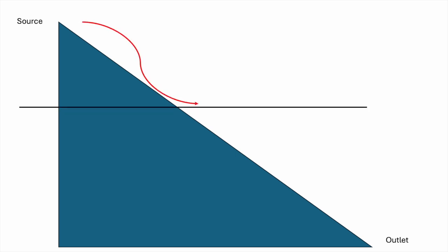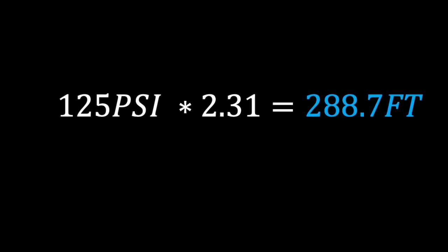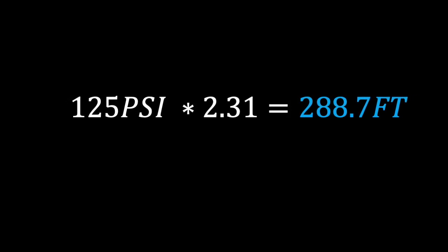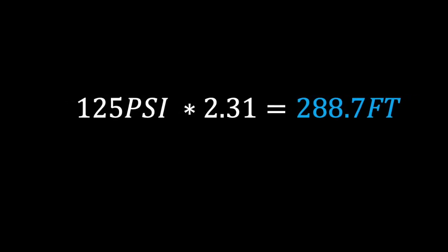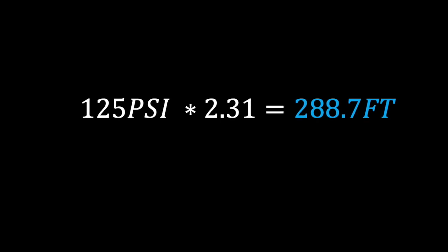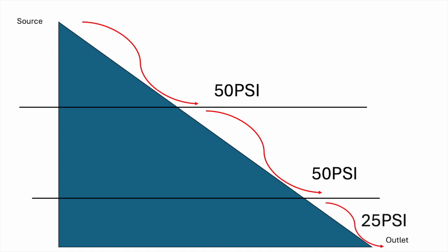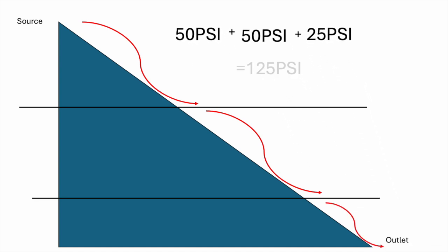Be careful: where there is a larger vertical distance, the hose may become overpressured. Fill the hose and measure the pressure at the bottom with a pressure gauge. The PSI value can be converted to head pressure by multiplying the PSI value by 2.31. This will give you a value in feet for the total height from top to bottom of the rise. You may have to complete multiple iterations with the garden hose and add the total PSI values if you have a large vertical drop available.